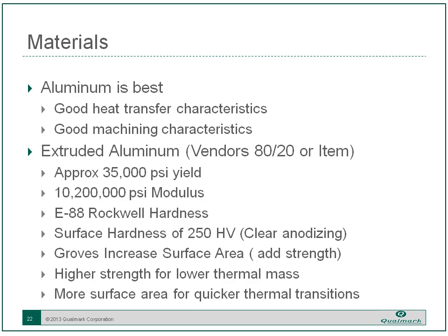When you think of the materials that you're using for a fixture, if you've ever designed fixtures for electrodynamic shakers, you have to forget everything you learned, because this is very different. Typically, aluminum is what we want to use. It's got good heat transfer characteristics, good machining characteristics. It's light and suits the purpose nicely, but transmits the shocks well into the product.